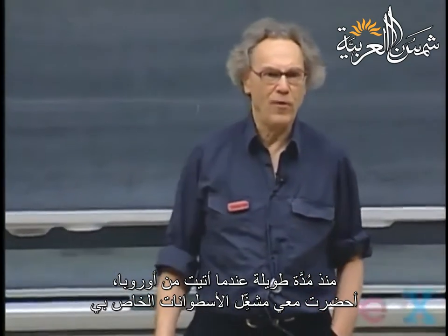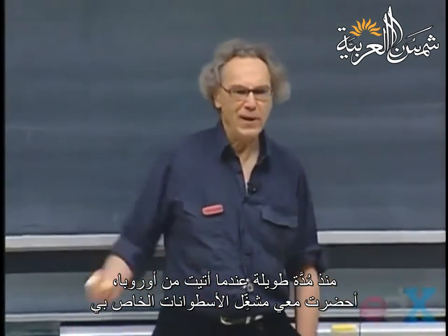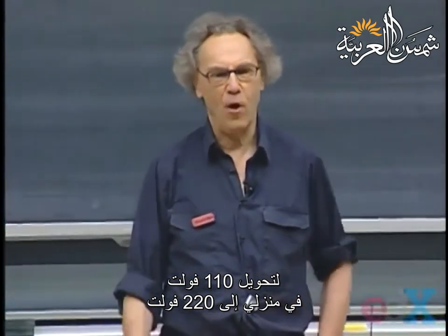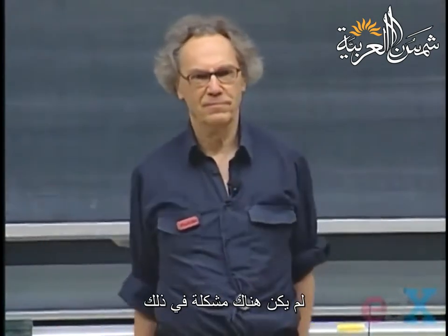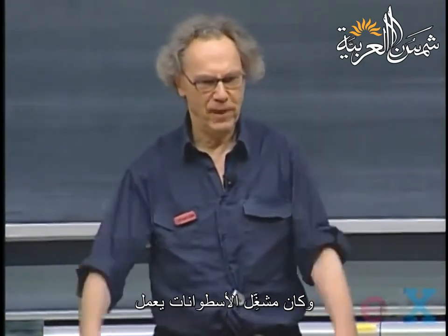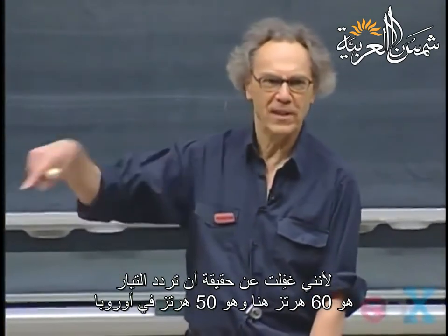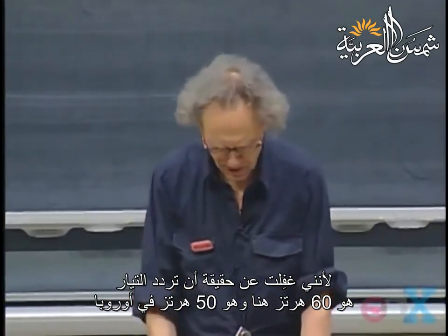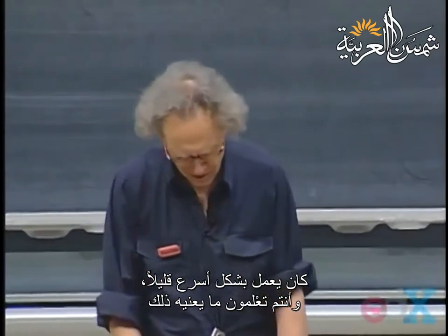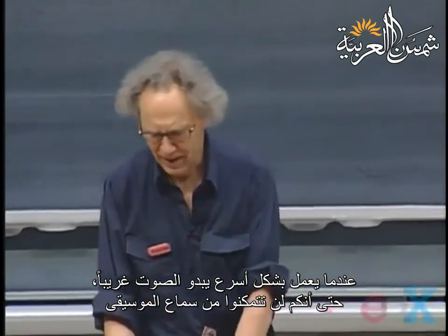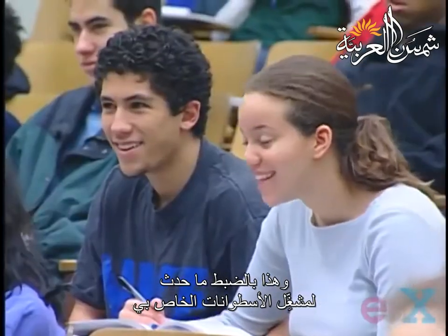A long time ago, when I came over from Europe, I brought my record player with me. The record player requires 220 volts, so I bought a transformer here so that the 110 volts at my home would become 220. That was fine. And so the record player was happy. It was running, but it ran 20% too fast, because I had overlooked that there are 60 hertz here and 50 hertz in Europe. So it was going a little bit too fast, and you know what that means when it goes too fast. It sounds very crazy, you can't even hear the music. And that's exactly what happened with my record player.